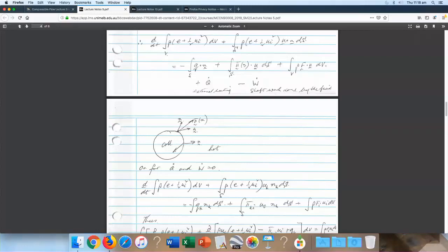It's like stress within the fluid. And there are two: there's the pressure and the viscous stress. And it's often helpful to treat the viscous stress separately because it's often negligible. At high Reynolds number, it tends to be negligible. If I was talking about honey, I'd have to include it for sure.